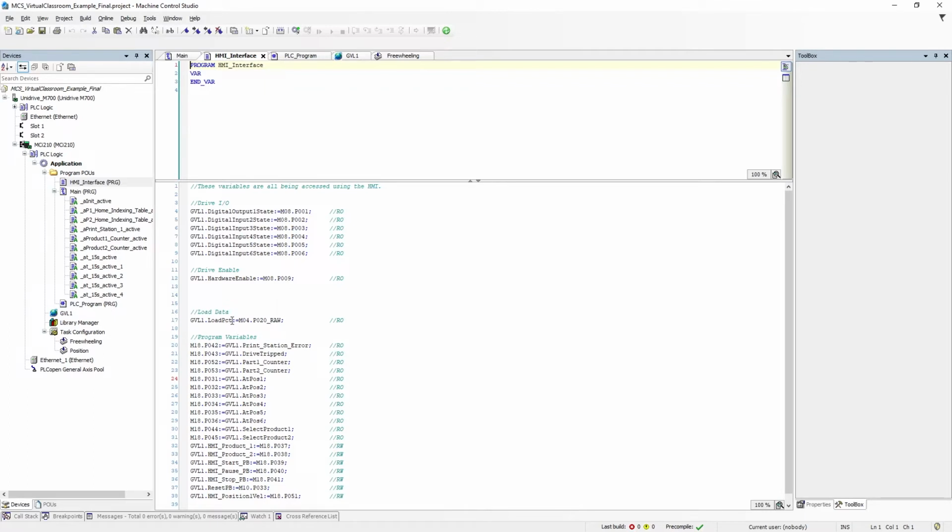By monitoring the load percent over time, which is a feature of the HMI, I've got that set up as a trend, monitoring the load percentage over time. I'm going to be able to tell if the mechanical components in my system are wearing. If I notice a general trend upward in the load percentage over time, that's an indication that the mechanical components in the drivetrain could stand lubrication, for example, or there's just something not right.